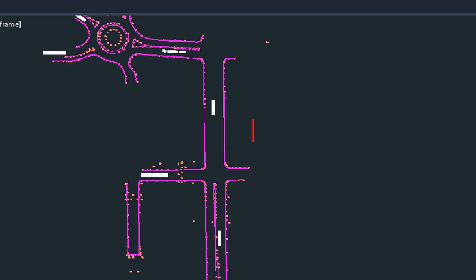Your point number range, you might want to just jot this down, is going to be 9, 8, 81, 82, 83, 8. So you're going to show that line between points 8 and 9. It's not really part of your traverse, but it is the line you used to establish a bearing reference. So let's go ahead and show that.